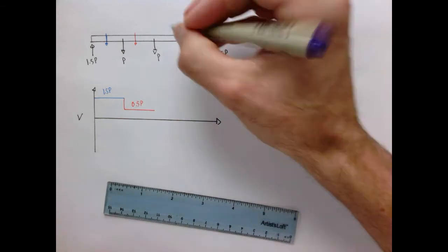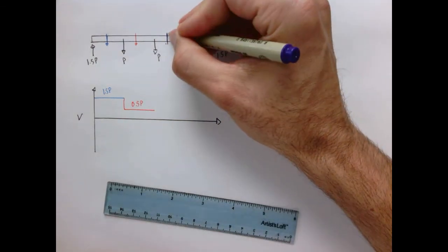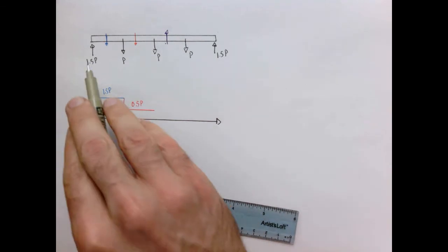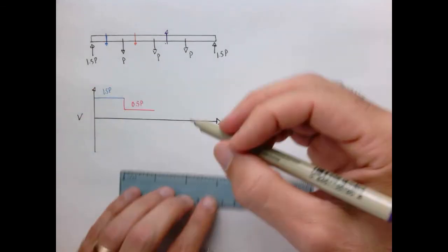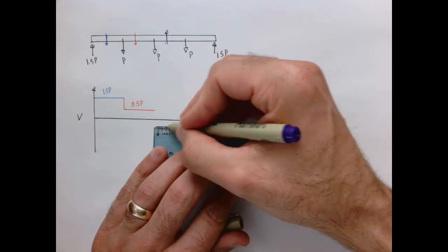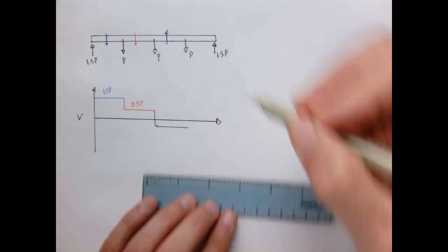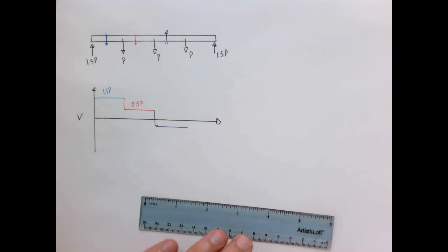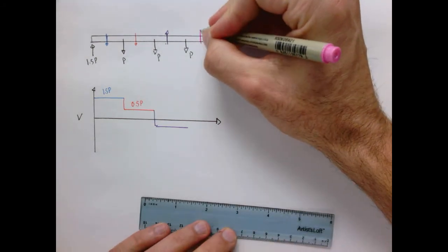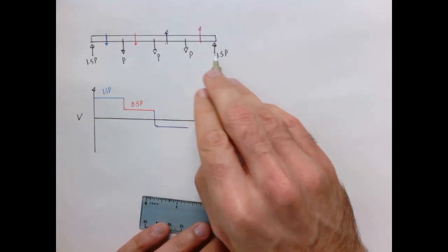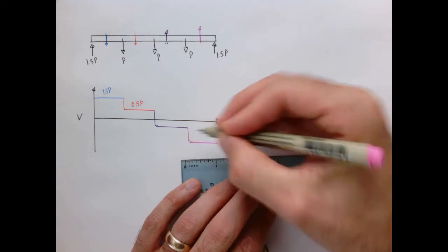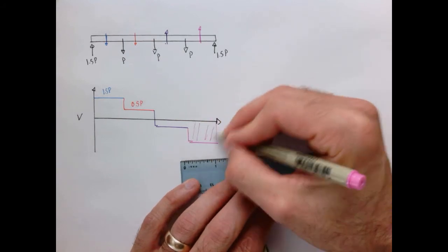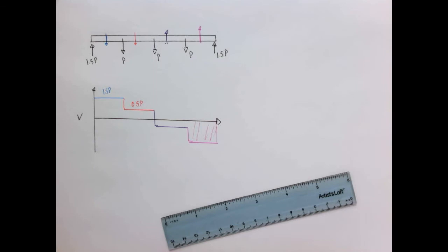Once I pass through this point, now the shear force has to be upwards because I have 1.5 up but 2 down. So now we jump something like that. And then finally, I think you probably see the trend now. If we come here, the shear force has to be 1.5 again. So my shear diagram has this kind of stair-step shape that looks like that. Perfect.